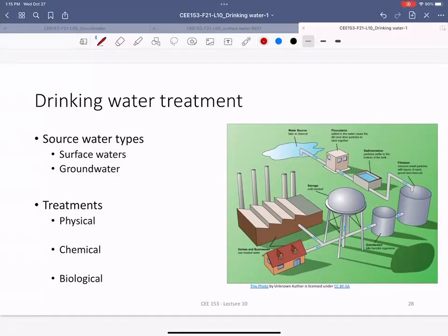But something else changes in groundwater. Because groundwater moves through soil, it dissolves a lot of salt from the ground. For instance, Florida has lots of limestone. When the limestone dissolves in groundwater, it changes the pH and the amount of carbonate in it. Limestone is very easy to dissolve, so you see a lot of sinkholes in Florida. The reason is the dissolving of the ground. Because of that, the carbonate concentration increases, which affects how corrosive or anti-corrosive the water is.